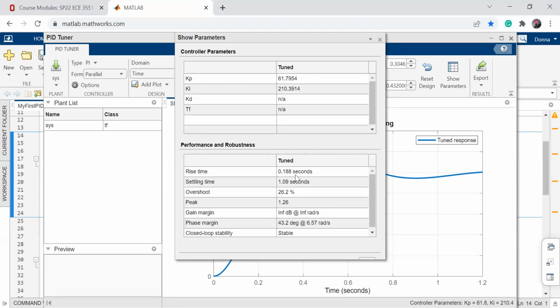So visually, because changing KI, KP, you might not understand, okay, how do I know I have to say KI is 1.5 instead of 1? But when you see the response, it visually helps you better because that's in time domain. Once you're happy, you can go and say, okay, what was the KI for this? So MATLAB behind the scene is solving the whole thing. Every single time it runs that block diagram, solves the equation, does the step, and just shows you the step.